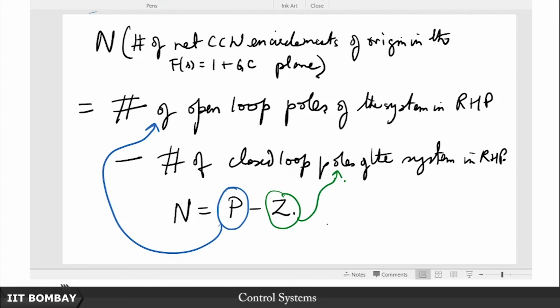But Nyquist does not tell you that it has to be 0. Nyquist tells you that the number of encirclements better be equal to the number of open loop poles of the system in the RHP. So sometimes people have this preconceived notion that no encirclements is the desirable thing to happen. This is precisely the kind of thing that led to this initial confusion, when people thought, how can decreasing the gain lead to instability and increasing the gain lead to stability from instability. But if your system is not open loop stable, Nyquist clearly and transparently tells you.